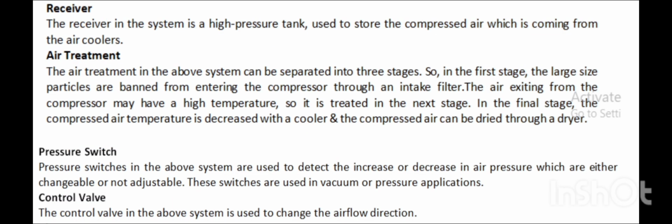The reservoir in the system is a high pressure tank used to store the compressed air which is coming from the air cooler. Air treatment. The air treatment in the above system can be separated into three stages. In the first stage, the large size particles are banned from entering the compressor through an intake filter.